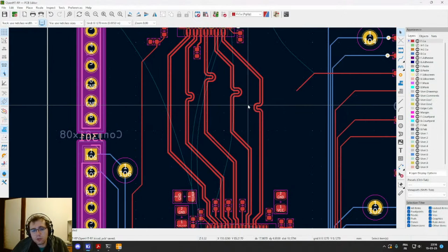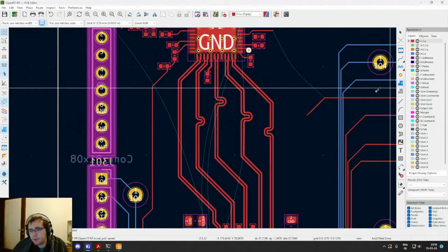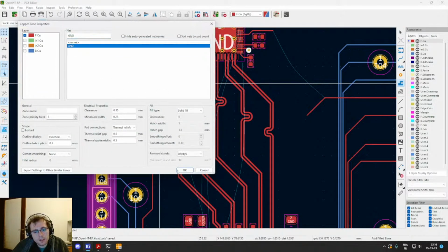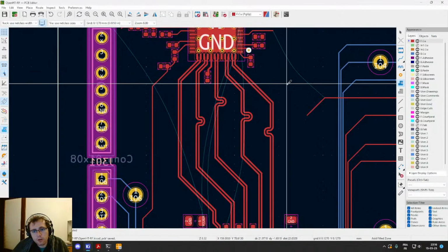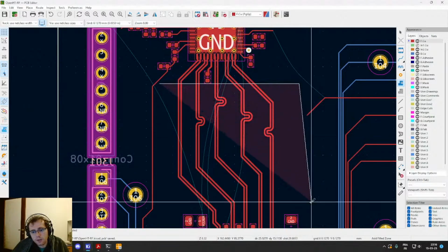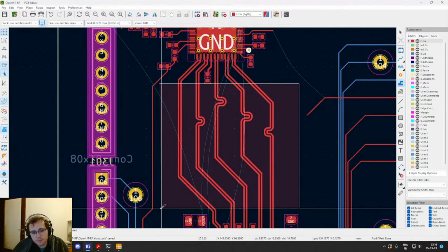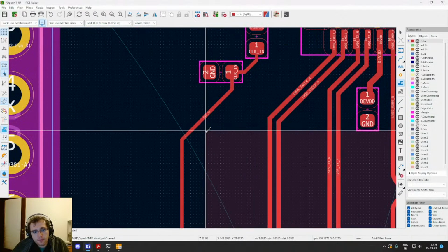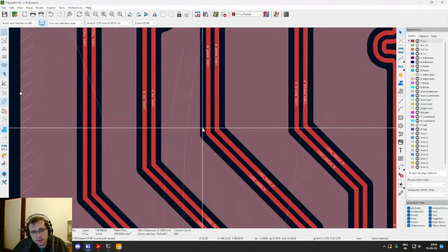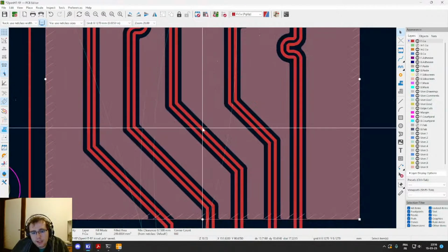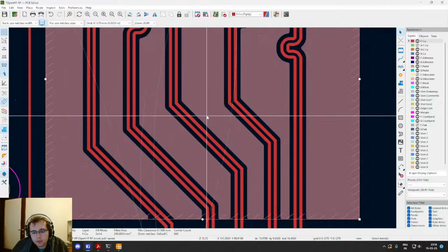I'm soon gonna go to sleep, so maybe we'll just finish with what I started with a few moments ago, explaining what we are gonna do for the ground around the LVDS pairs. So the thing is, basically, from a theoretical point of view, any track is considered as an inductor.